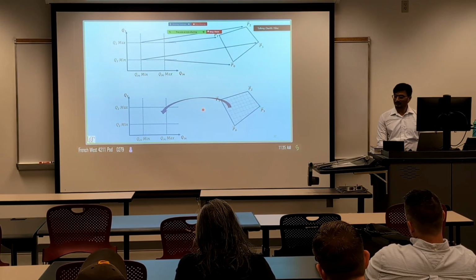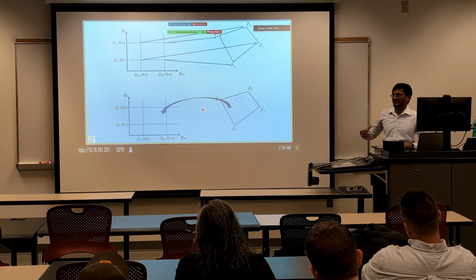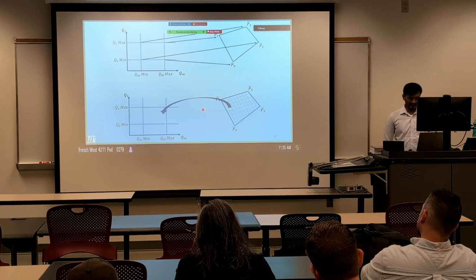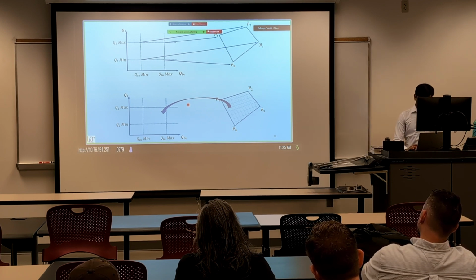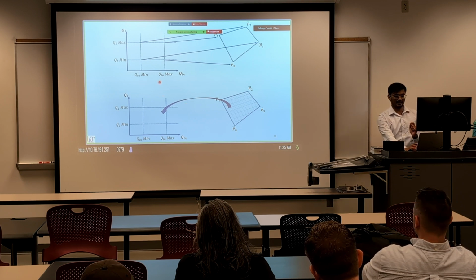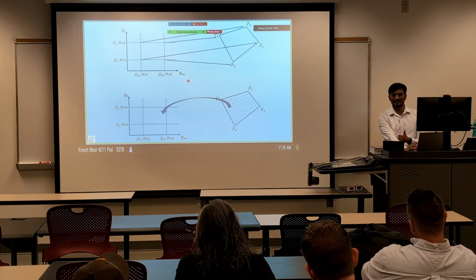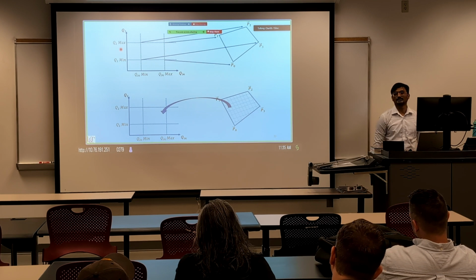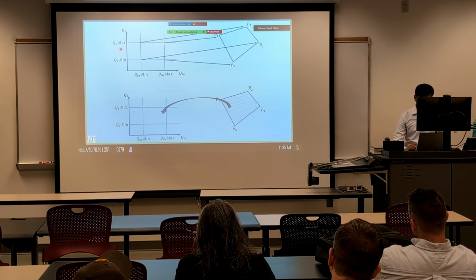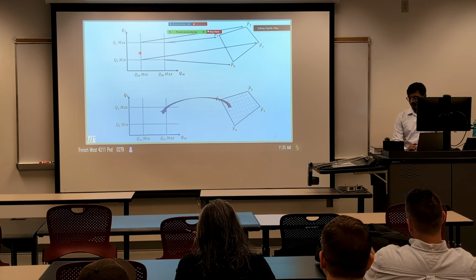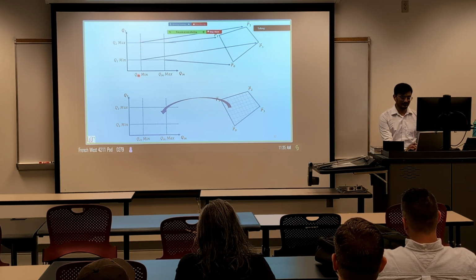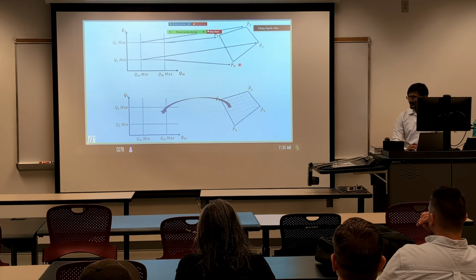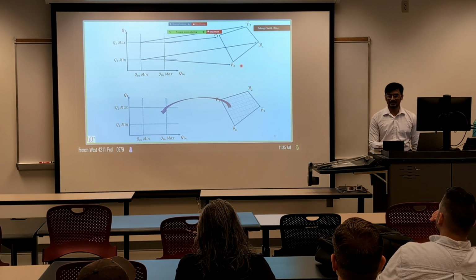Now what we did was, suppose we have a set of flow rate values to work with. Then we first choose the minimum and the maximum Q in values. Remember, we are only dealing with Q in and Q2. And then we choose the minimum and the maximum Q2 values. And at these specific 4 flow rate values, we calculate the corresponding pressures using the algorithm I mentioned. So it's only 4 calculations.